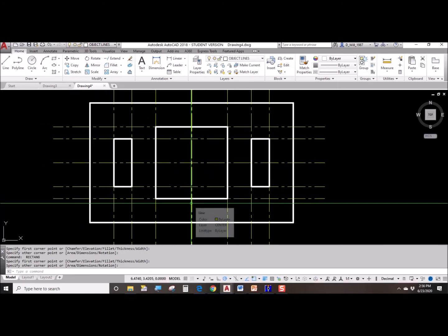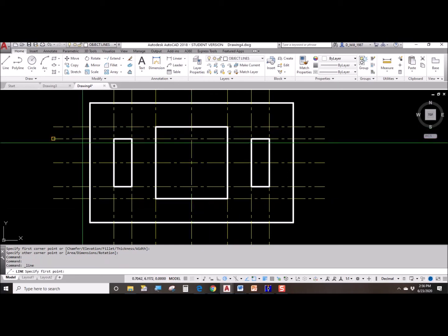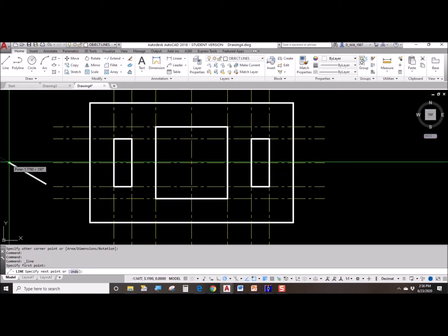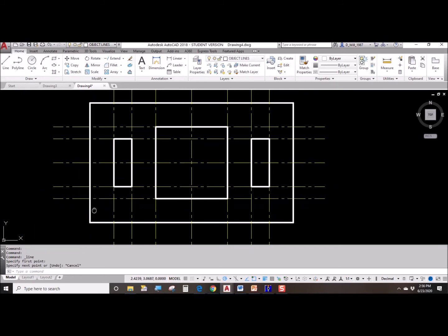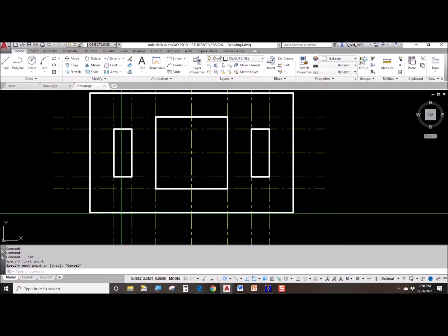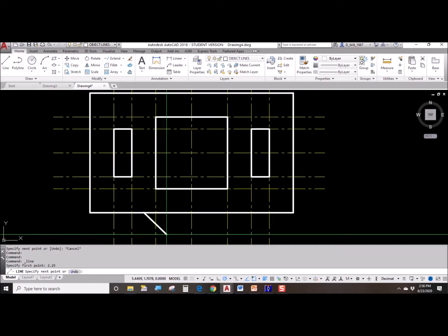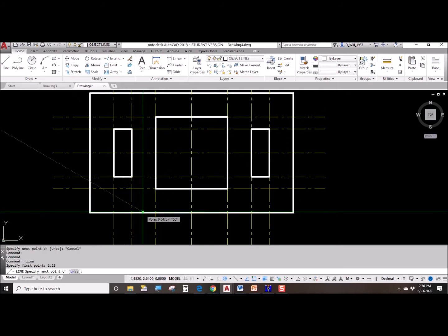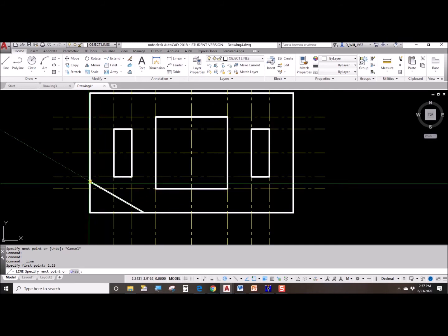All right. My last step is going to be, let's knock the corners off of this thing. So the angle I want to draw it is 30 degrees. I already set my polar to that. The distance from the bottom corner is 2 1/4 over. So there's a few ways to do this. You could hover over the corner if you have object snap tracking turned on, point to the right and type in 2.25. Right, that's 2 1/4, and that's exactly how far away from the corner you started. And now I'll just go up at 30 degrees and I can stop there.